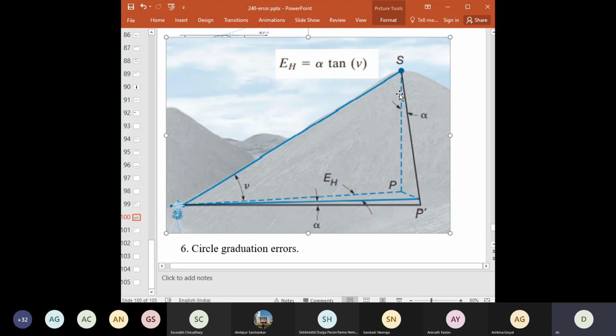Because of this, these two geometries are getting into consideration for all calculations based on my total station, because it's also following a level which is not properly aligned. The horizontal angle difference results because of the positioning difference of point P and P dash at two different orientations. P is the ideal one, P dash is what is coming up because of the misalignment.